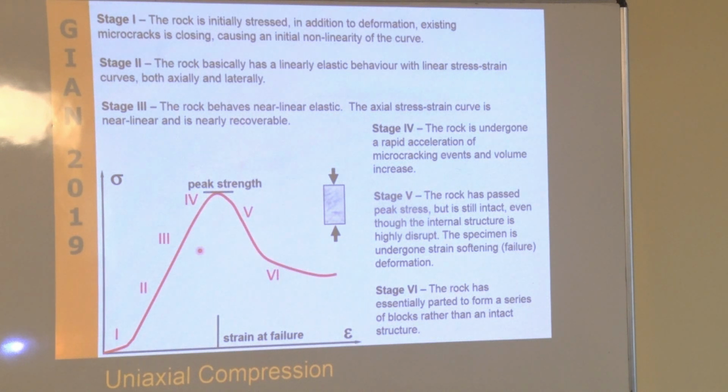And then at some point the rock tends to reach sort of a residual state, that is the residual strength that the rock still has, because when it fractures, it's not a nice final fracture, it has some waviness, some asperity, some roughness, and that roughness is helping you to not completely disintegrate and fail along that particular plane. Okay? And the residual state of your rock mass. And that is really what you are looking for in mining.